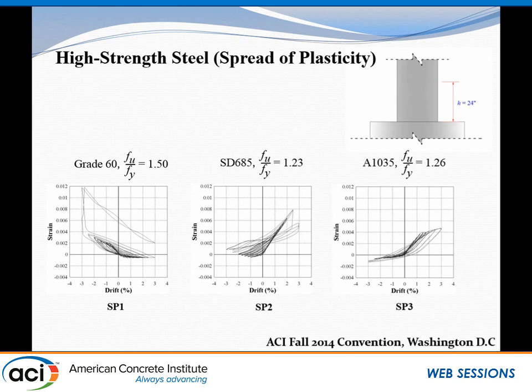But for the high strength steel A1035 in specimen SP3, the stress is around 0.67 of the yield strength. It seems that at this level, specimen SP3 did not reach the yield strength at the same distance. However, it should be reminded that strain gauge reading is very sensitive to the crack location.